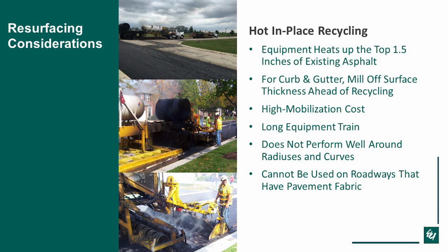So with that, it's a little bit difficult to get around really sharp curves, and obviously you can't do it in cul-de-sacs, has a hard time getting around some radiuses, and then, as mentioned before, it cannot be used on areas that have pavement fabric because the scarifying unit won't be able to tear up the fabric.